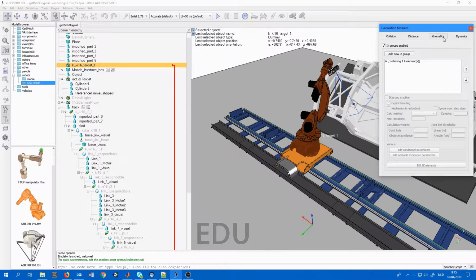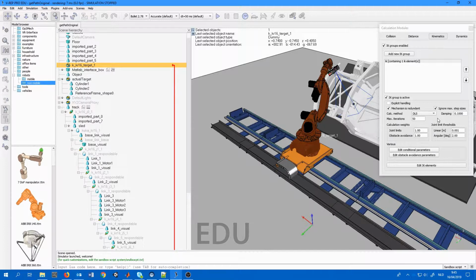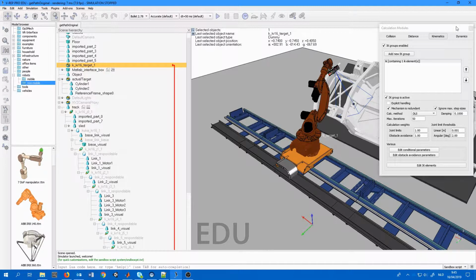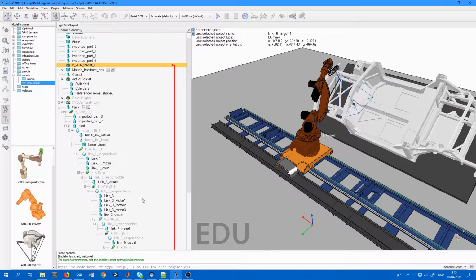If you have inverse kinematics and you want it to be continuous, so if you move the end effector with the controller and you want continuous movement, then you have to use damped least squares. That's maybe a tip; it's logical if you know what methods do that. This is more continuous than the pseudo inverse, but yeah, might be a good trick.